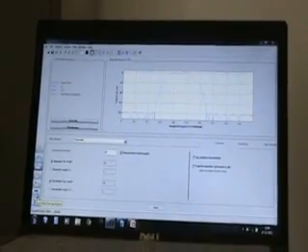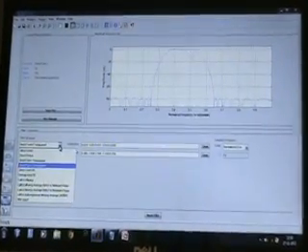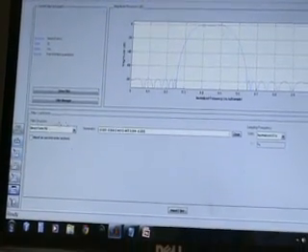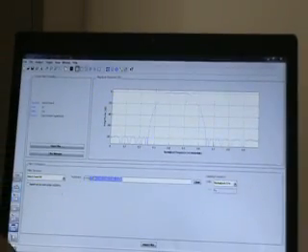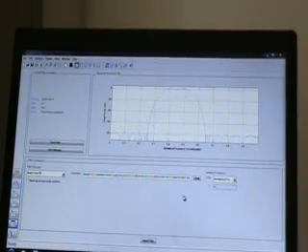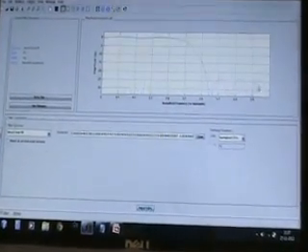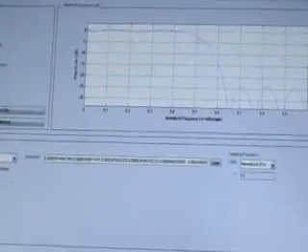Then we have an option called import filter from workspace. Here, as we are designing direct form FIR, we select that from the filter structure, and in the numerator we'll be entering some values. These are the values of a low pass filter, and we click on import filter. This is the low pass filter whose filter coefficients were given in this numerator.